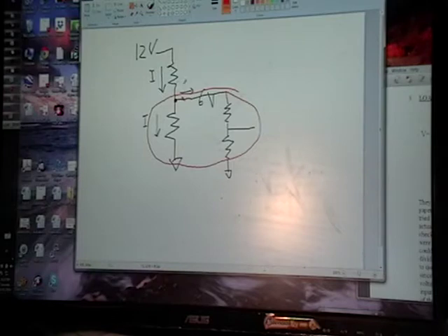But what happens is some I, let's call it I2, ends up going out this way. And now this is actually, whatever that I is, minus I2. And since these 2 currents aren't the same now, so the current through the top resistor isn't the same as the current through the bottom resistor, this voltage right here isn't going to be the same.